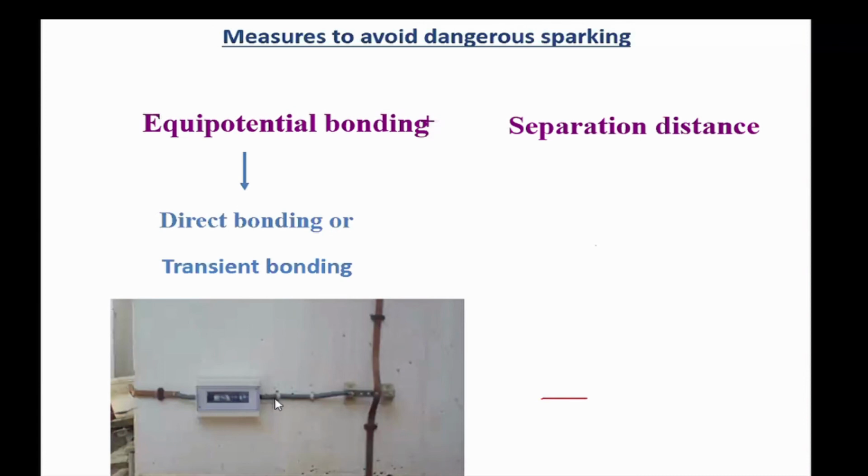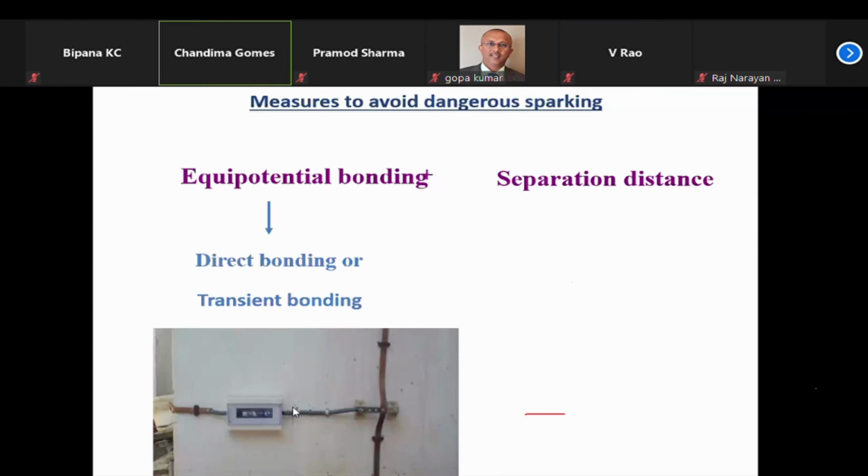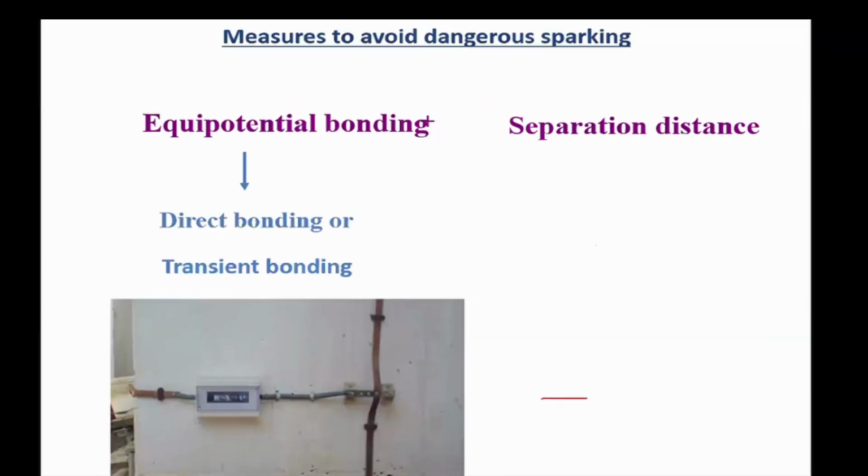This is usually done when you want to connect, for example, the power earthing system and the communication earthing system, which are not favorable to be connected under normal operating conditions, but should be connected under lightning or transient conditions.